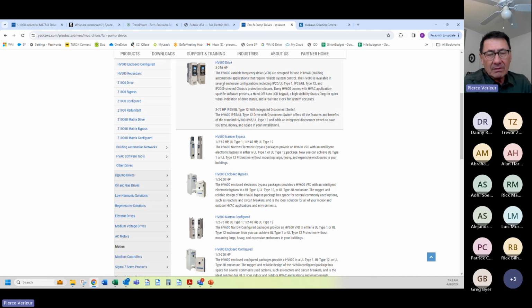And it was great, but you didn't get variable speed. Today, using bypass, in my humble opinion, is a ridiculous expenditure of money. It costs another 25, 30%, and it's completely useless because drives just don't fail at anywhere near the rate that they used to fail in the 1980s, when bypass was conceived and productized. However, being a specification-driven industry, specs are somewhat not up to date in many cases, and we have to bid them, and they require bypass. So we have all sorts of bypass options for the drive.